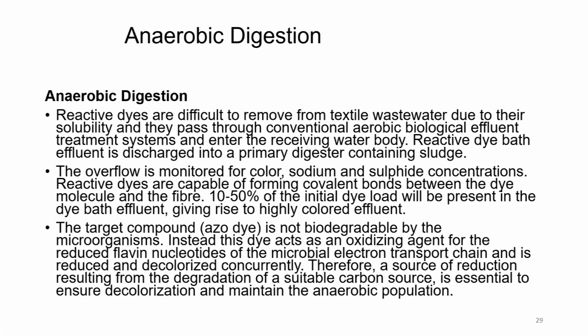Instead, this dye acts as an oxidizing agent for the reduced flavin nucleotides of the microbial electron transport chain and is reduced and decolorized concurrently. Therefore, a source of reduction resulting from the degradation of a suitable carbon source is essential to ensure decolorization and maintain the anaerobic population. So, a lot of chemistry keeps happening even in the anaerobic digester.